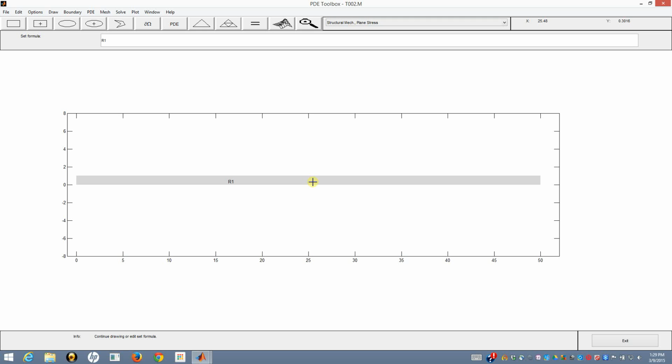I can come in and make an object. This is if you didn't have this one feature in this. If I had this, the deflection of a bar is going to be PL over AE. Now, if you look at this thing, and you pay real close attention, looking at this, the force is P, the deflection is this. So this K from that equation would be AE over L, wouldn't it?